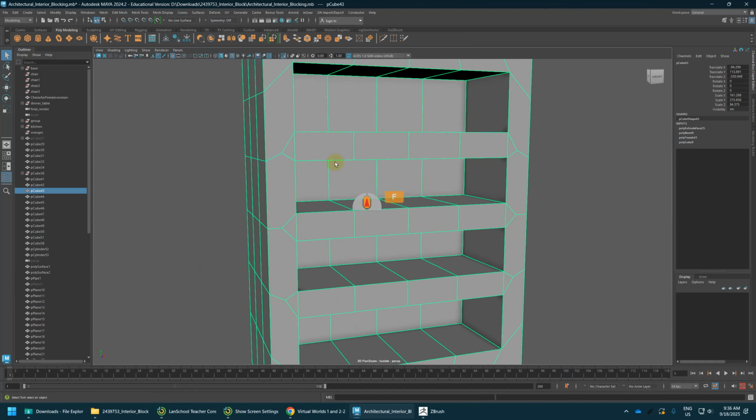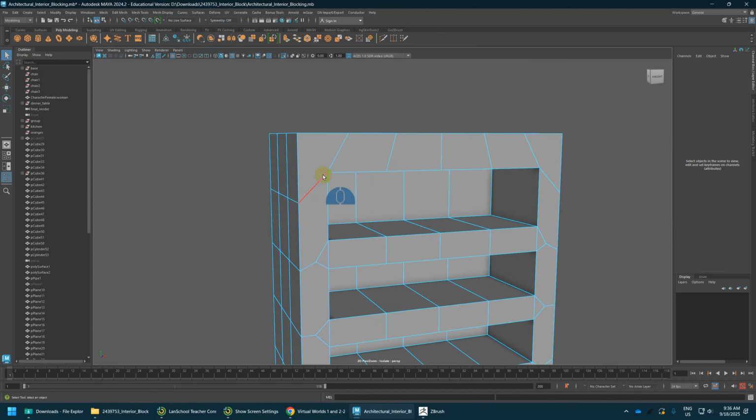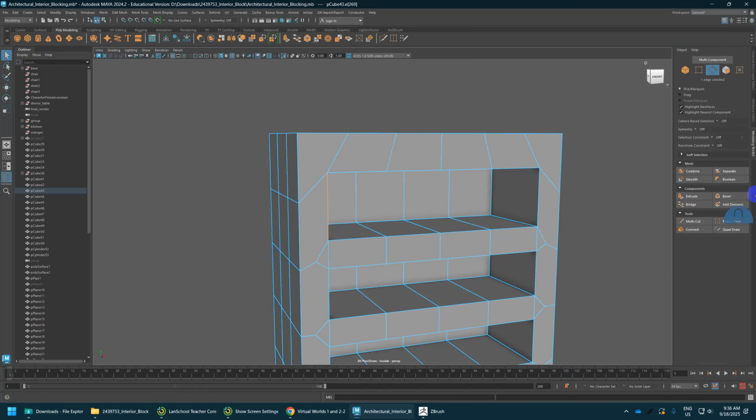Basically, this has more than 4-sided polys, okay? So a lot of software will not know how Maya is actually interpreting polygons with more than 4 sides. This has 5 sides, right? So not the cleanest. Usually you'd keep these edges going through the mesh, or you avoid this by basically doing a target weld. Sorry, let me do this in vertex mode. So then you can have tris, you can have quads. You can't have more than 4 sides. Software doesn't know what to do.